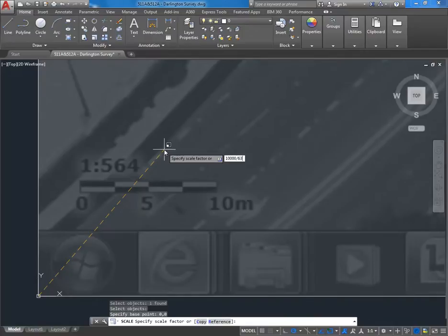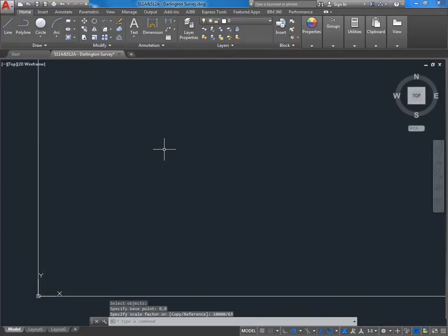If you've got a printout of a drawing that you want to change to a different size, you can measure the scale bar, divide those numbers with a calculator, and then put that as your scale factor on a photocopier, and use that approach without even touching your computer. So that will always work. So basically the formula is the size you want it to be divided by the actual size, or the size it is in your file. So the size you want it to be divided by the size it is.